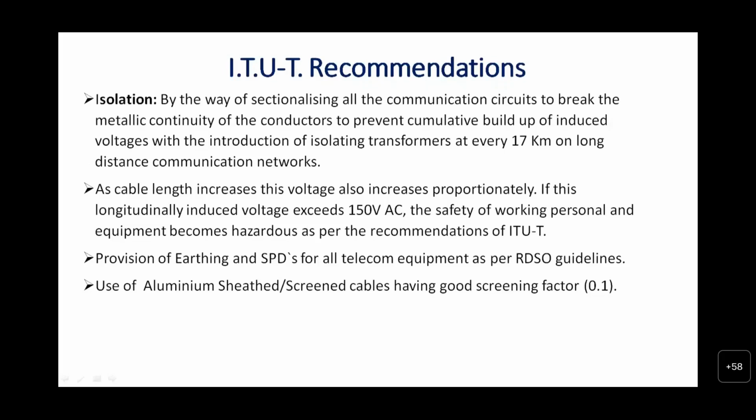If this longitudinal induced voltage exceeds 150 volts AC, the safety of the working personnel and equipment becomes hazardous as per the recommendation of ITU-T. Provision of earthing and SPDs for all telecom equipment as per RDSO guidelines is to be mandatorily utilized. Use of aluminum sheath or screening cable having a good screening factor of 0.1 should be ensured.